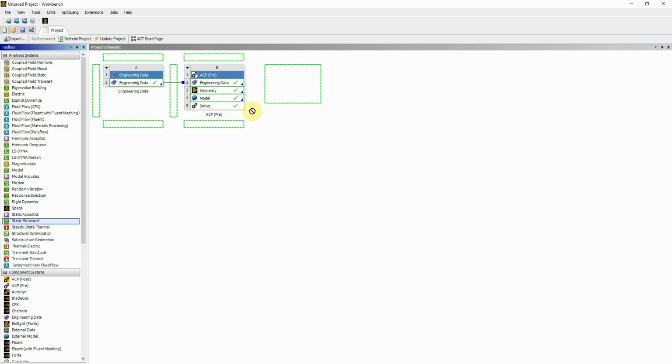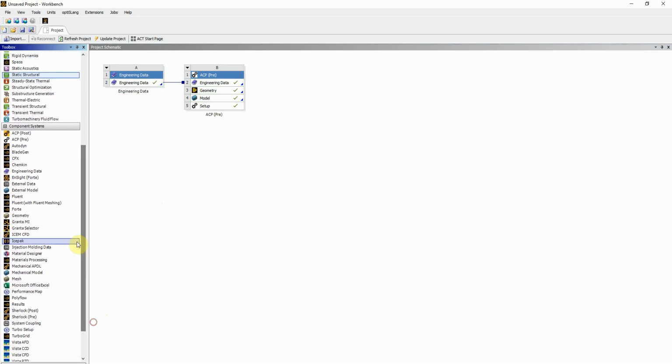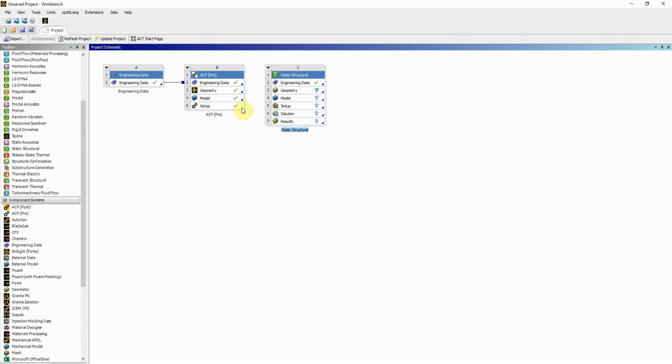So it's static structural. Static structural, drop it there. Select the model. Okay, so it's a little bit tricky. What we did there was, you can't just drag and drop onto that one. You have to have a static structural and you have to bring it in as a solid composite, not a shell, but a solid. So once you transfer that, it will automatically delete everything else that was in the static structural, and now it's going to use the model from there in order to run the simulation. So what we're going to do is double click on the model.